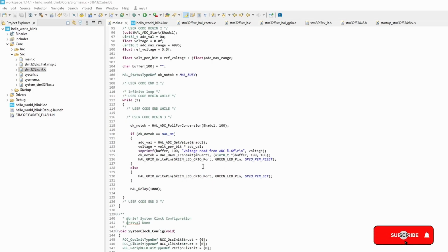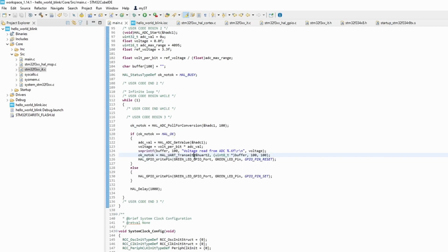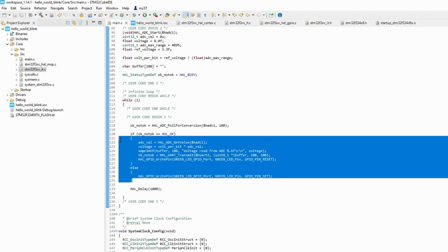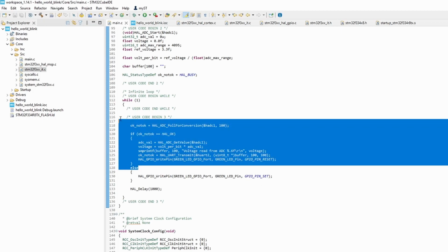So what we can do is print out a message every second or every 100 milliseconds that says hello world, and while we do that we can set up a user interrupt. So there's a user button on the Nucleo board, on my Nucleo board, so we'll connect that to an interrupt, and while there are messages being printed out, we can interrupt the main flow of the program, print out a message from our interrupt function, and then return to our main function here.